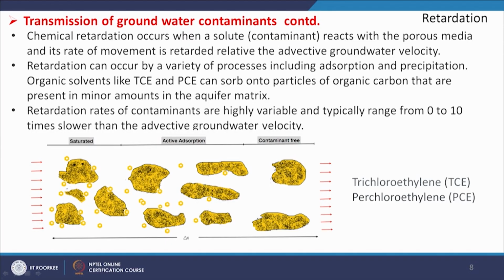These materials may have some interactions. If there are no interactions, there will be no variations and all the water and pollutants will go. But if there are some interactions, the pollutants will be adsorbed by these materials present in the aquifer. So, at the front head, the amount of pollutants passing through will be reduced. That is called the retardation.